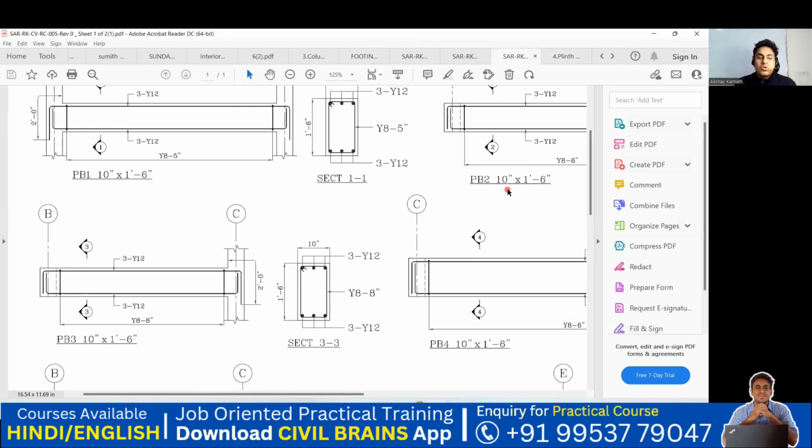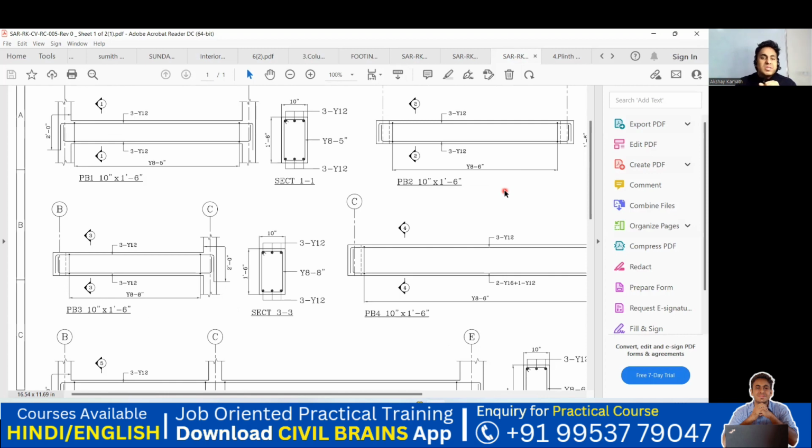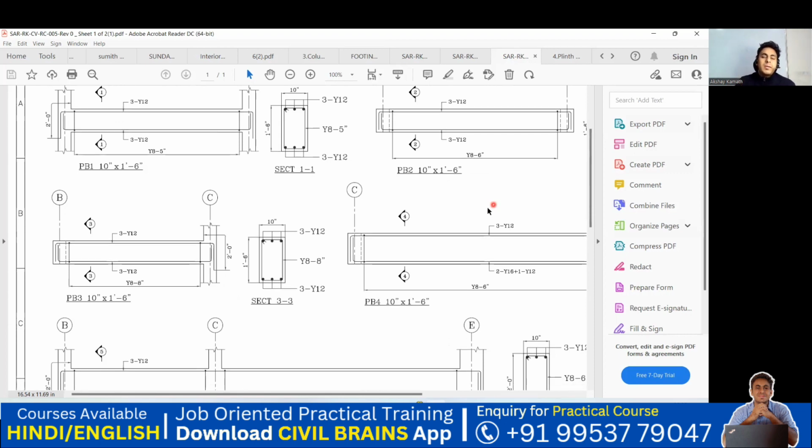So here they have gone with 250 mm. You can go with 250, but I would rather say go with 230 mm. That is the best size to have, because 1 inch is 25 mm, so 25 times 10 comes out to be 250 mm. So 250 mm is the width they have given, but the chance of giving 10 inch is very less.